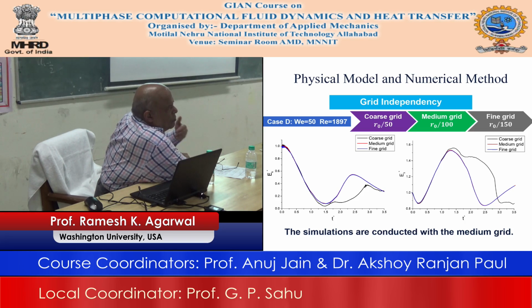My philosophy is always that in CFD you have to first formulate the problem, then understand the physics that you want to capture, then decide what is the simplest model that you need to capture that physics and which code has that model, and then the results can be trusted. So always follow these four or five steps, and I think you can use CFD very effectively.